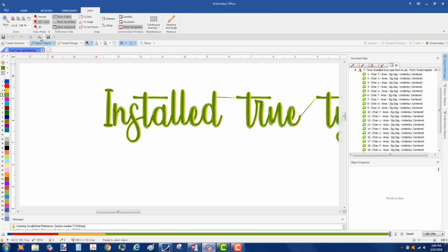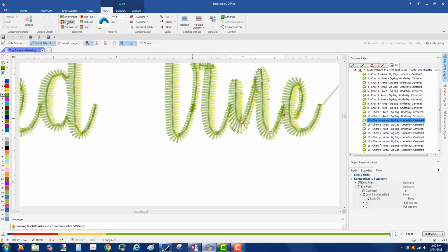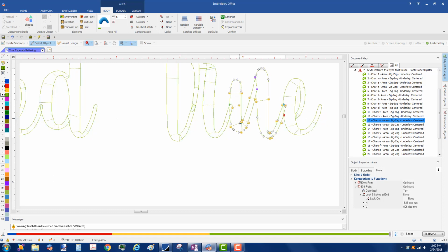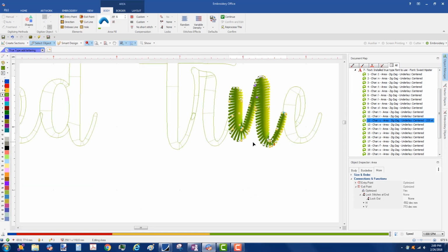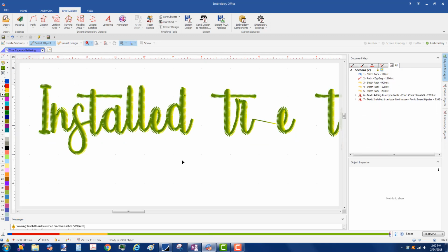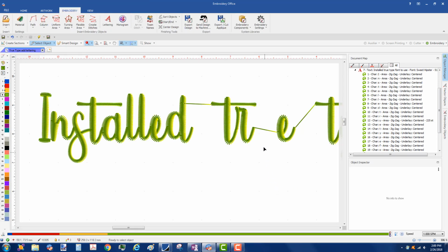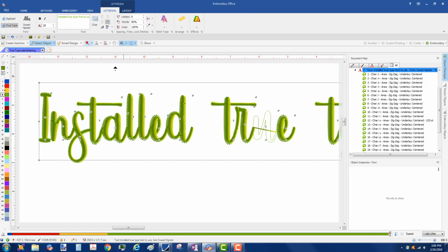So we'll move on through all of the letters and we'll make any directions, adjustments that are needed. Any spacing that's needed. This I don't like. I'm going to add on a couple of directions probably. You don't want your nodes to overlap because it creates intersections with the math and you get funky results. So we'll try and see if we kept that S. And it looks like, well, looks like we lost that one. So we're just going to keep, again, playing around with reprocessing until it finally accepts it. Again, probably fine on export, but I like to see it. I don't like it missing.